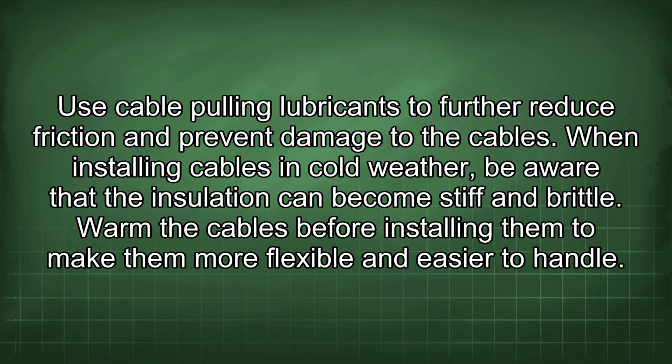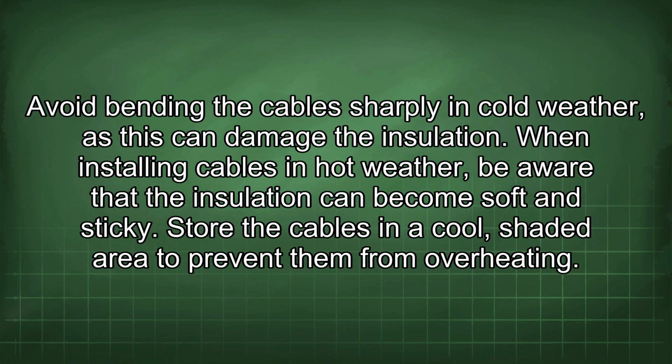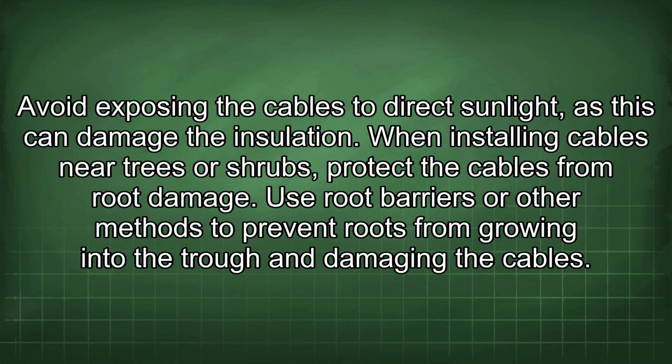When installing cables in cold weather, be aware that the insulation can become stiff and brittle. Warm the cables before installing them to make them more flexible and easier to handle. Avoid bending the cables sharply in cold weather, as this can damage the insulation. When installing cables in hot weather, be aware that the insulation can become soft and sticky. Store the cables in a cool, shaded area to prevent them from overheating. Avoid exposing the cables to direct sunlight, as this can damage the insulation.